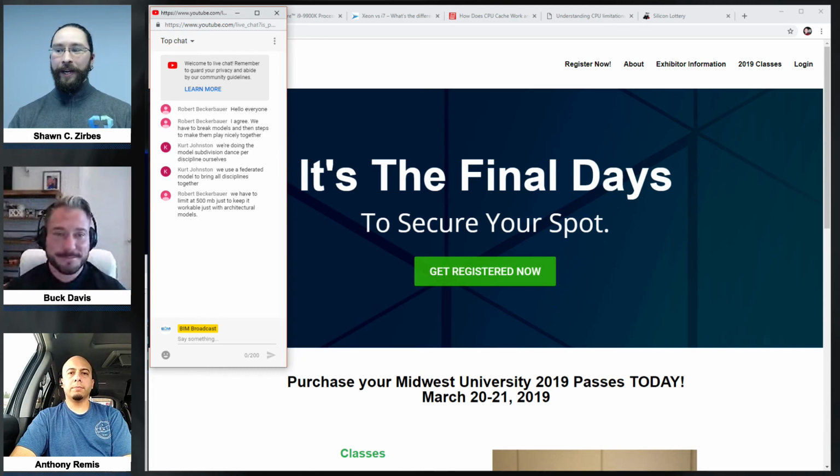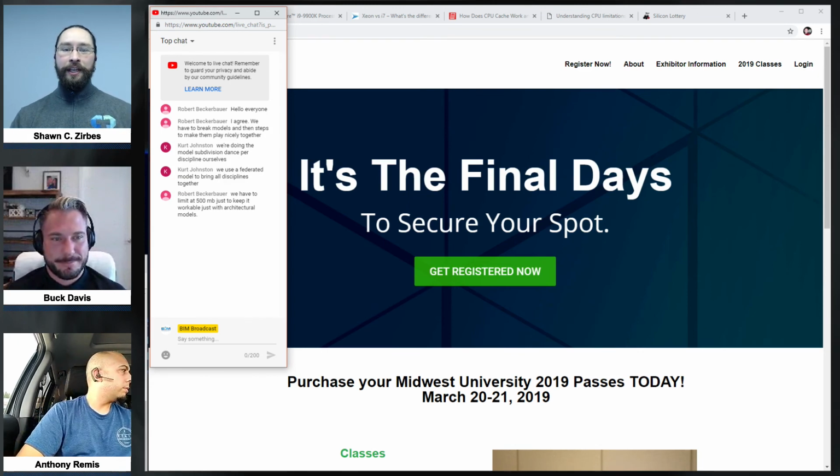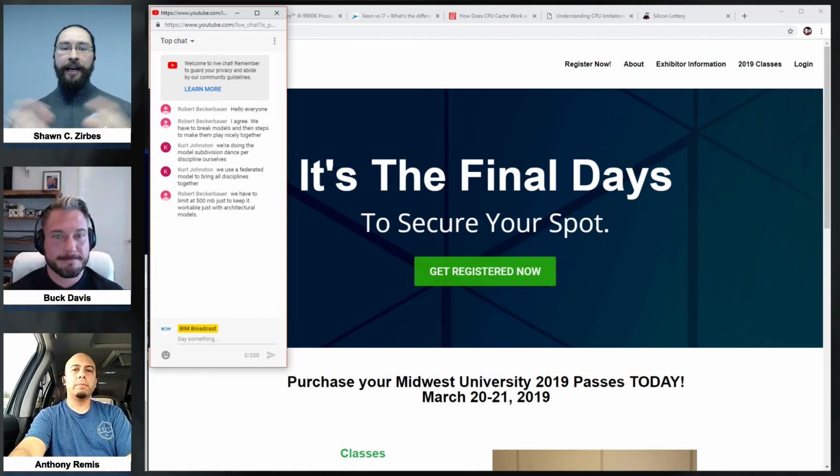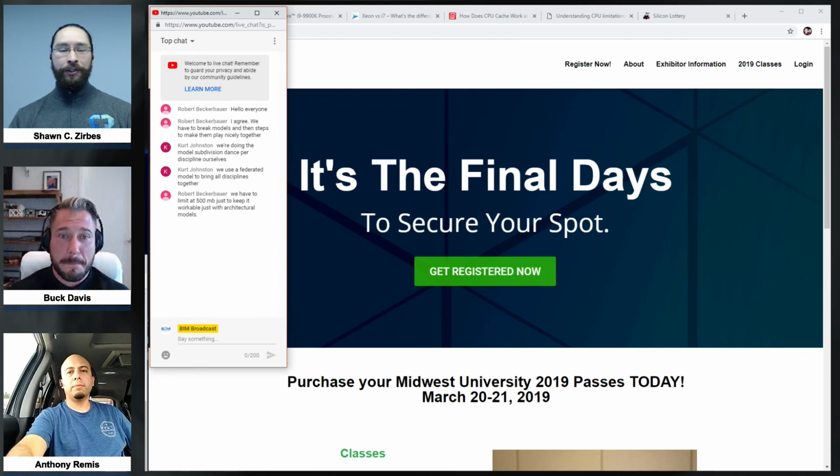Right. Just to kind of jump in on this conversation, I see Kurt and Robert out there making comments on this. Robert was saying that he's got 500 meg limits on their models. That's where they cap it because they can't go bigger or it becomes too slow. I see that problem a lot. And that's partly due to hardware, but again, it's in large part due to Revit. Kurt Johnson was saying he's using a federated model. So what that means is they're taking multiple models and linking them all together to federate this, or to have some bits and pieces and parts all over the place, but then they got one main model where they're doing a lot of their documentation. That's what a lot of people mean with that. So that, again, it's all due to limitations of Revit being single core.